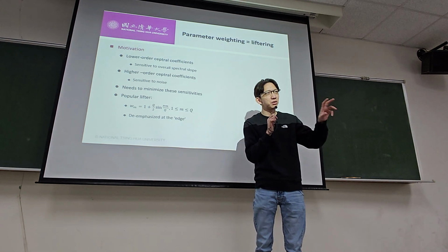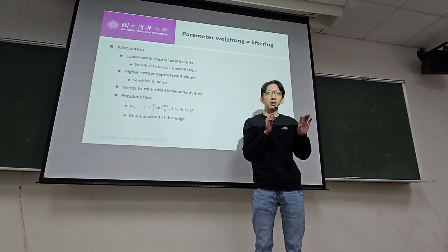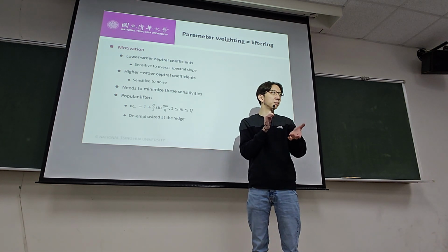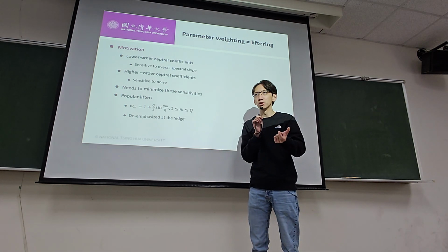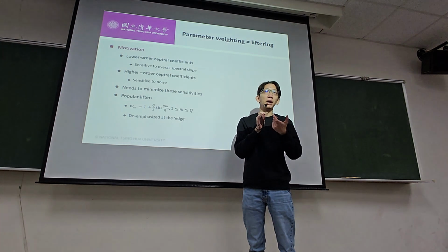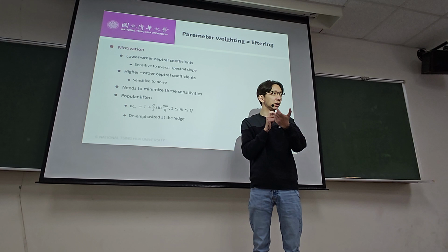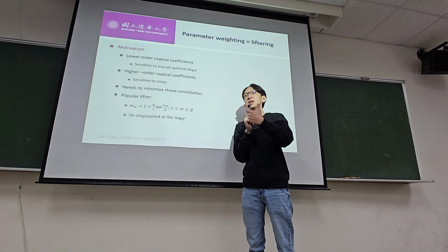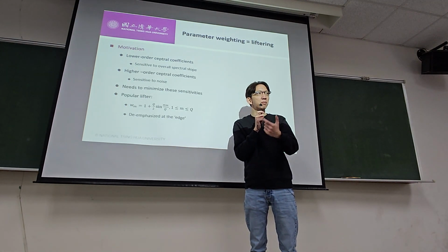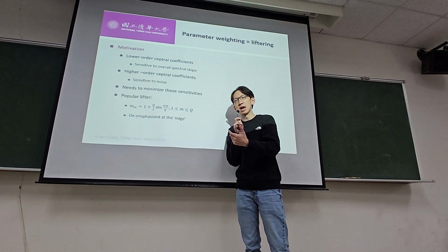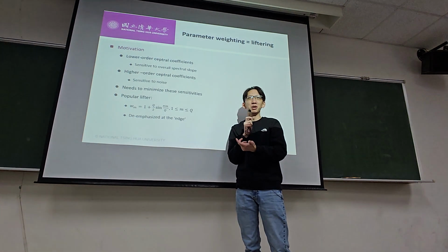You also need to be aware of some very fundamental things that people do: take a segment, do the blocking, apply the window function. This doesn't just apply in the time domain; the same process applies in the cepstral domain, because it is the same thing. You'll find out that the cepstral domain is actually an alternative time domain representation.